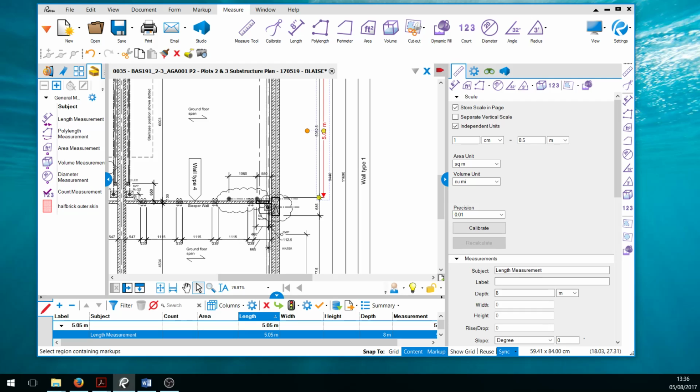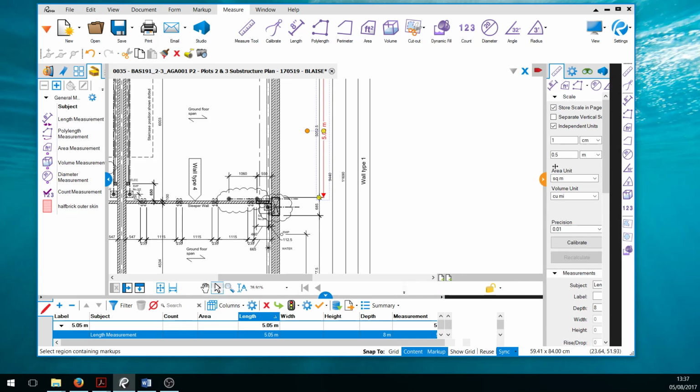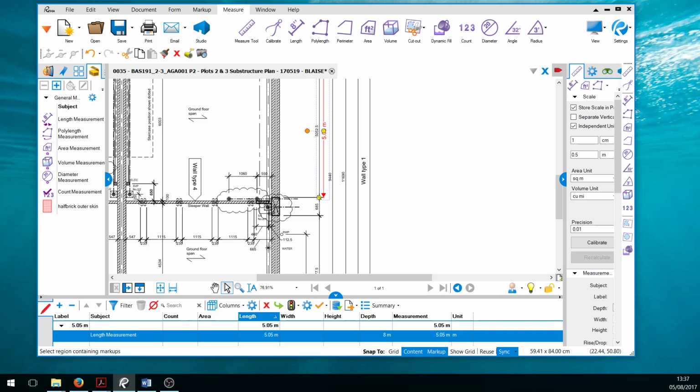As I said, these are just default and basic generic tools that come with Bluebeam. Don't change these ones that are shipped with Bluebeam, because all you'll do is overwrite them. They just won't behave the way you think. If we want to create our own tools, we need to duplicate these and then edit those using this dialog. But we'll do that a little bit further down the line.